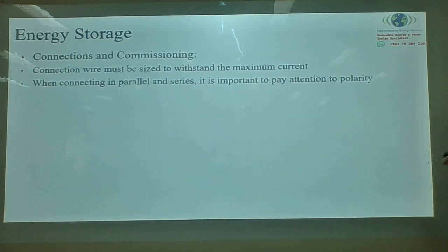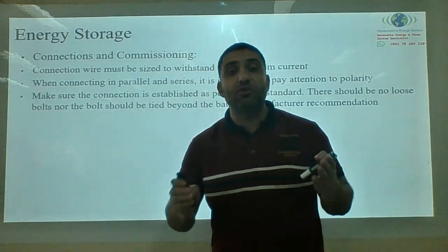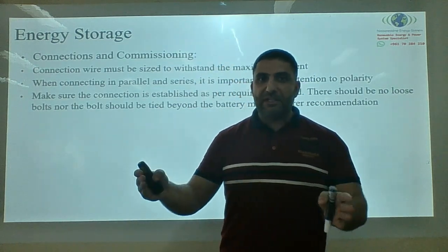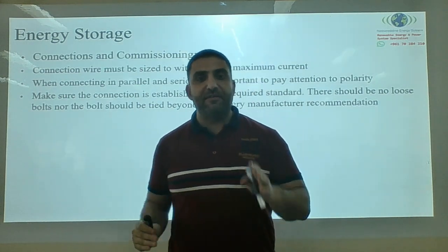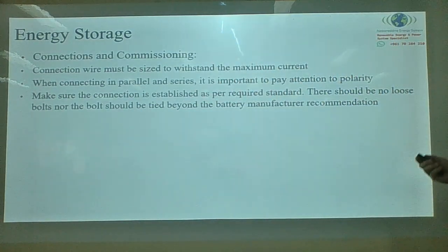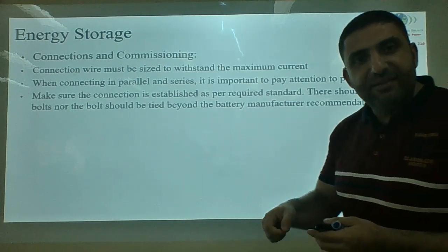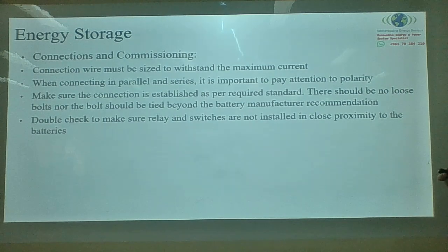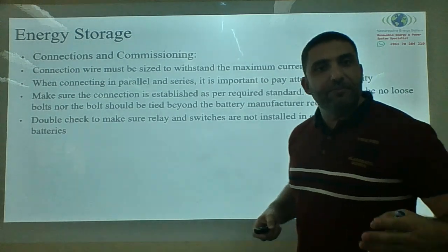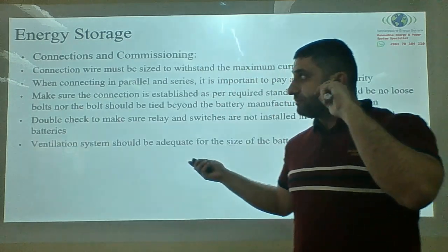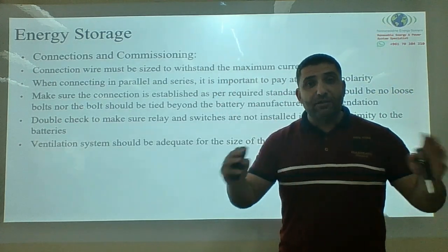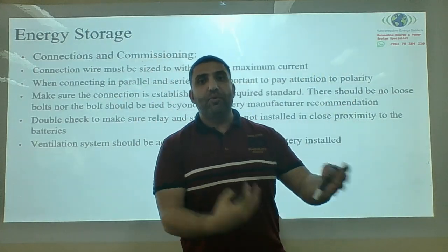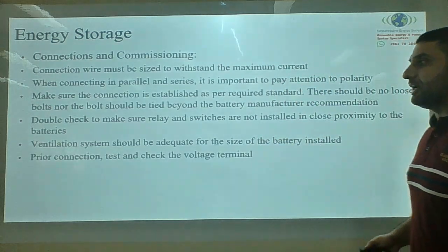When connecting in parallel or series, it's important to pay attention to the polarity. When you connect in series, positive to negative, positive to negative. Connected in parallel, positive connected to positive, negative to negative. It's very important, guys, to make sure all the bolts are tight. There's no gap. Don't allow for sparks or anything to happen. Double check to make sure relays and switches are not installed in close proximity, especially if it's not a sealed one. Make sure the ventilation system is working. Sometimes maybe you put in an exhaust fan or a cooling system, depending on where you are located.